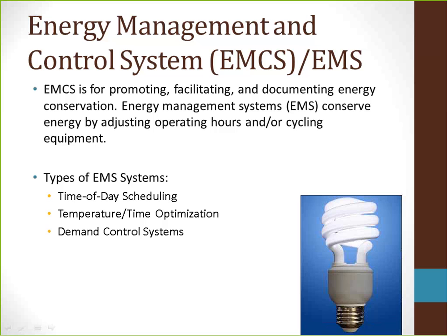Typical interruptible loads are heating, ventilation, and air conditioning systems, air compressor motors, and manufacturing processes that can readily be interrupted or delayed. In addition to generating energy savings by shutting off unnecessary loads, these systems reduce monthly peak demand charges on electric bills. Demand control systems provide for a large number of control and monitoring points.